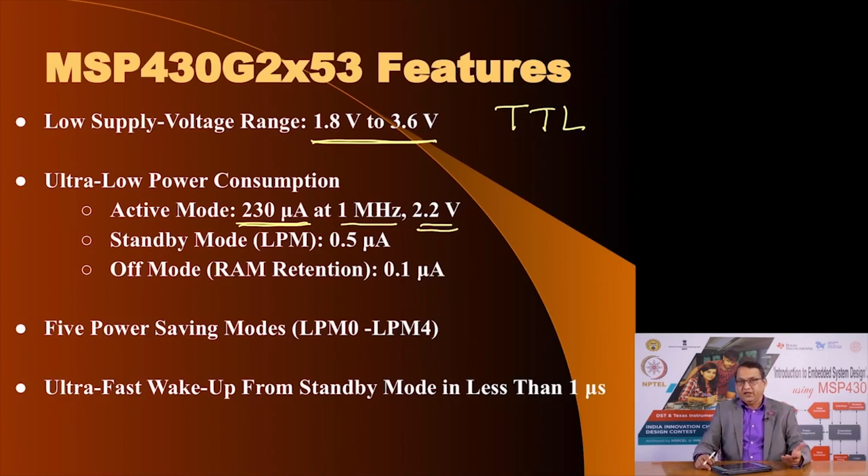If you operate it in what is called a standby mode, which is one of the low power modes that is available, it consumes a mere 0.5 microampere of current, and you can imagine that if you have a coin cell or a button cell, even on a single button cell, for how long this microcontroller can continue to operate, provided it has large periods of time when it is in a standby mode, but once in a while it could wake up and do real work and then go back to the standby mode.